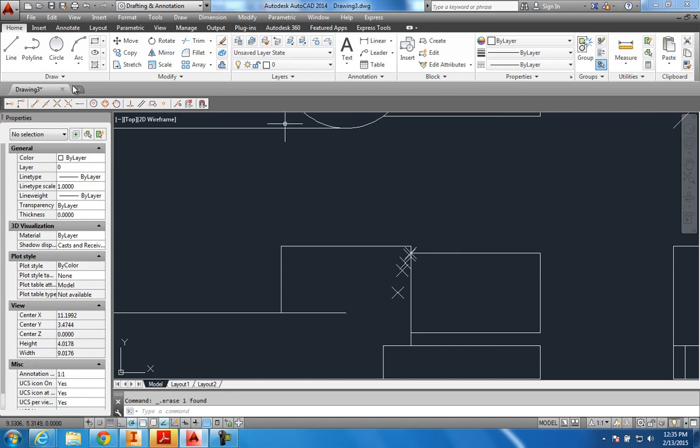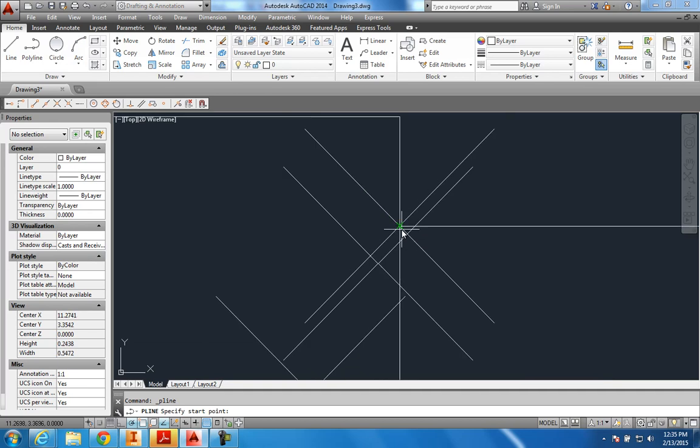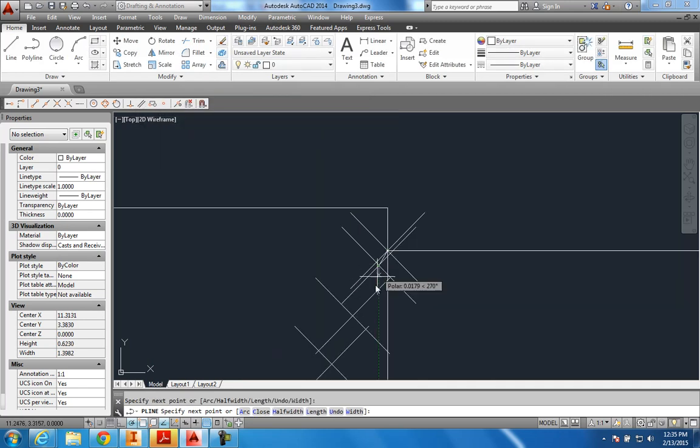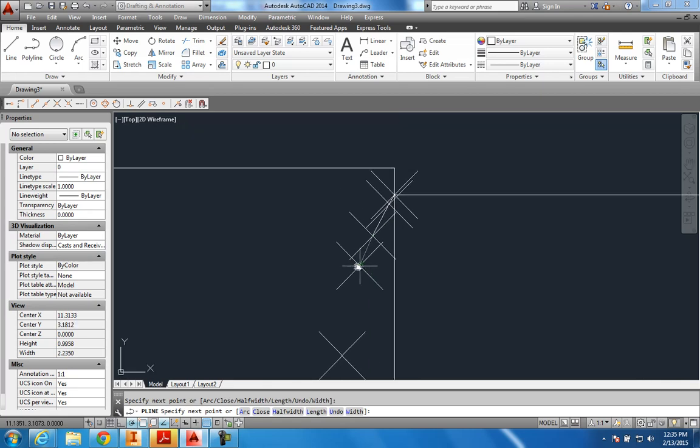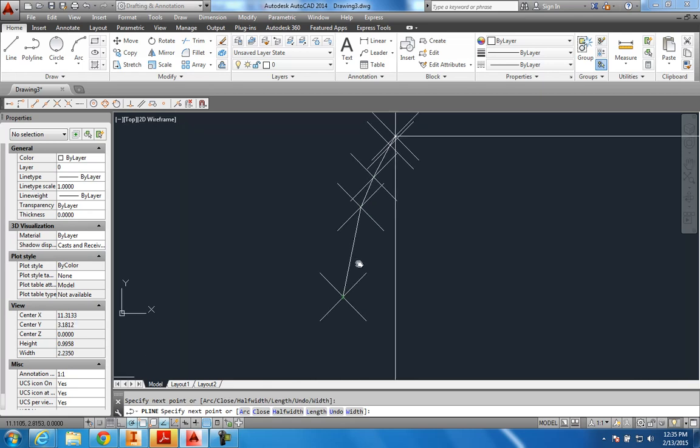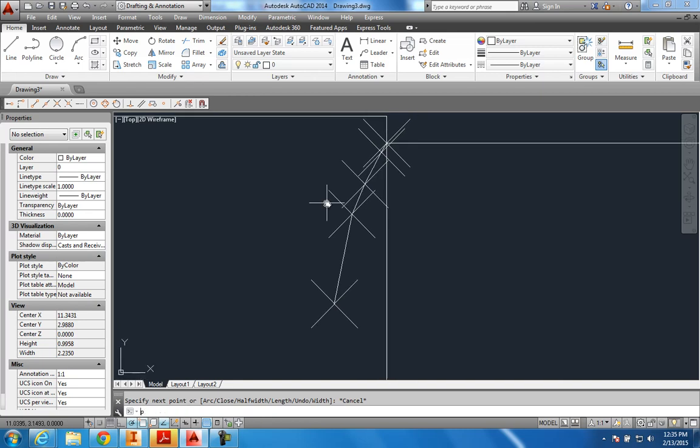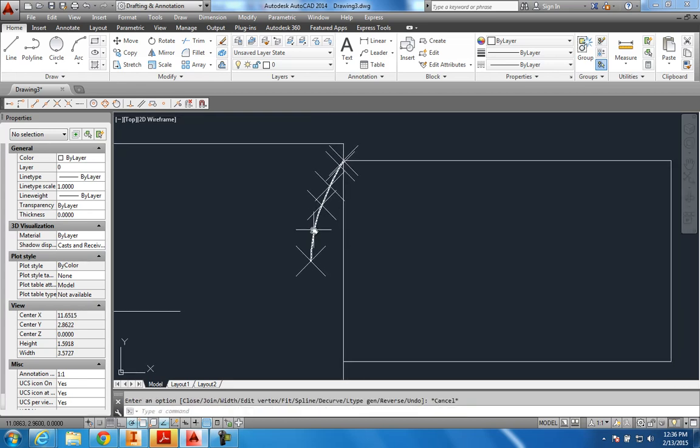And all you have to do is come up here and just go to Polyline. Make sure your node's turned on. This one is. Just go ahead and start snapping your points. Like I said, turn your nodes on. Make sure that's on, which it is. Catch those nodes. And after you get that, we'll do a PE, Polyline Edit. Grab that line, do a fit, smooth it up a little bit. And after you get that done, go ahead and turn your format, your point style off.